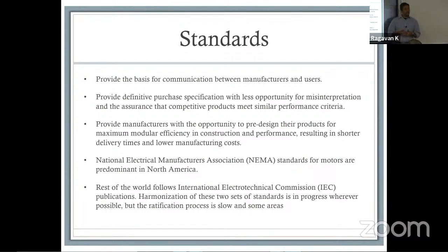If you don't do that, you end up in a scenario in which your motor sends out EMI and could disrupt somebody's pacemaker, for example. You might end up with acoustic noise that causes somebody's hearing aid to start making very loud and unbearable noises, right? What we are doing is high frequency switching, causing a very high voltage to collapse very quickly by switching back and forth. When you increase the frequencies, that EMI radiation is going to be substantially higher. So you need to make sure you are accounting for that in your design, and that's what standards specifically test.